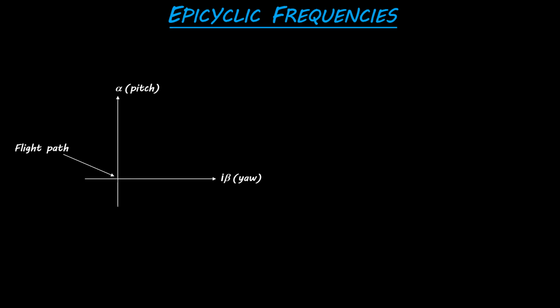What we've got is that our flight path is the center of this. Essentially, we are behind the projectile looking forward in the direction that it's moving. Our flight path, our velocity vector, is located at the origin of this graph. So that's the reference frame of this picture. Now, from the velocity vector, we're always going to have this yaw of repose.